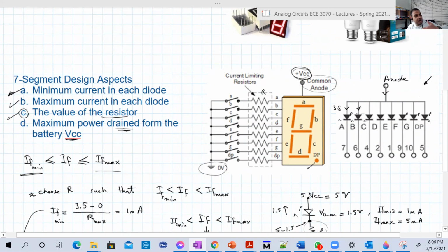You can include the decimal point or not, but for our example, I will exclude the decimal point. I will just talk about the most famous 7-segment display, just the name 7, not 8. So in that case the total current here is 7 multiplied by 3.5 milliampere.